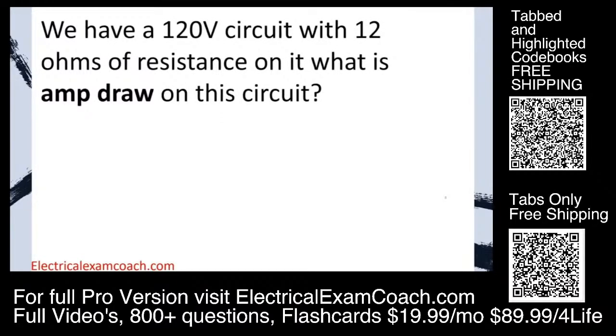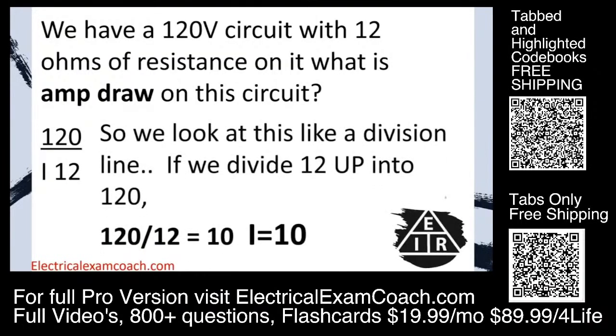What is the amp draw on this circuit? Well, what I love about formulas is we just plug in what we know. We know we have 120 volts. We know that we have 12 ohms of resistance. And we're going to look at this like a division line. We just take 12 and divide up into 120. We set it up like this. 120 divided by 12 equals 10. That lets us know that there should be 10 amps of current on this circuit.